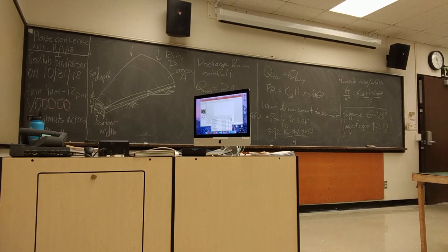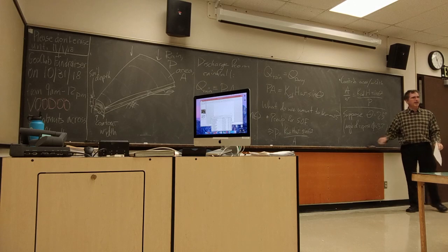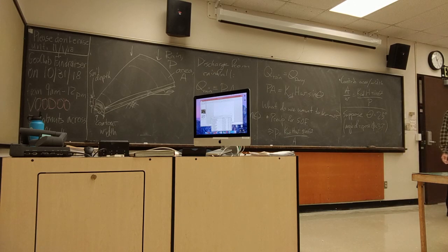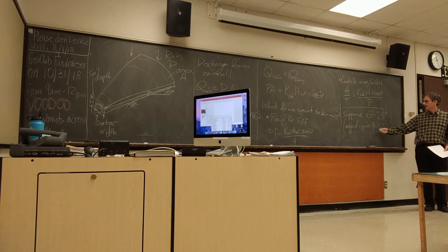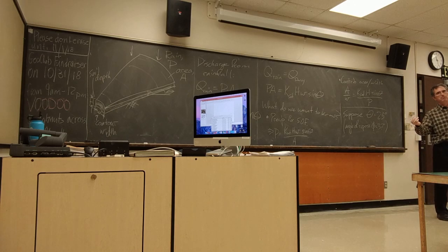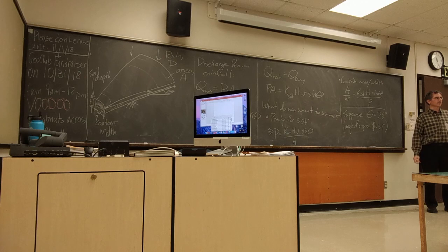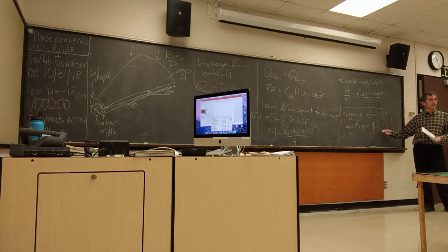Anybody remember we set up, yeah, 21 degrees, that was better. So we said if we've got zero cohesion, or neglecting cohesion, there's going to be some angle below which no amount of saturation will cause it to fail as a landslide. Conversely, there's an angle above which some level of saturation, if we have zero cohesion, will set off a landslide. And for zero cohesion and a 37 degree angle of repose, that angle was 21 degrees.